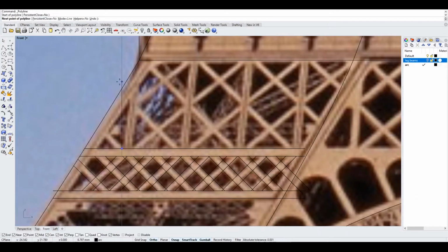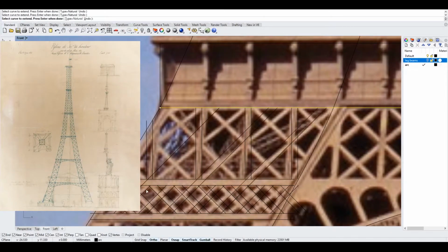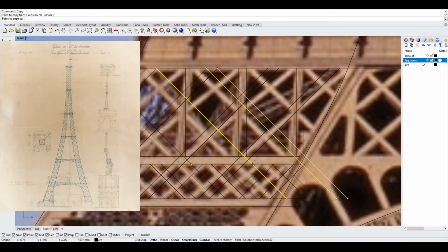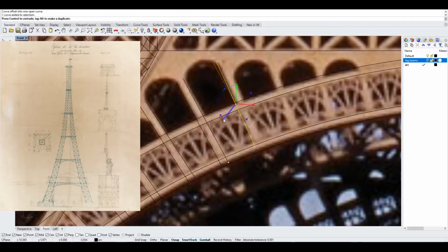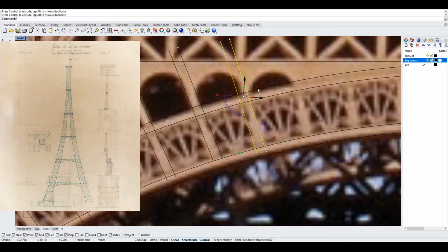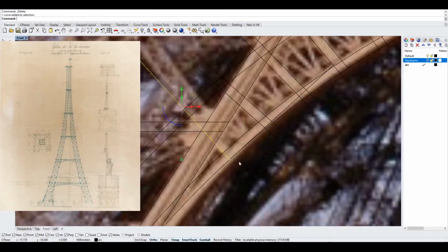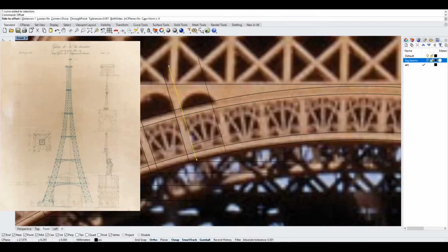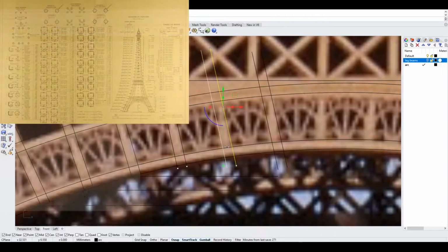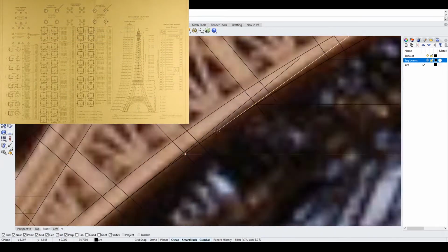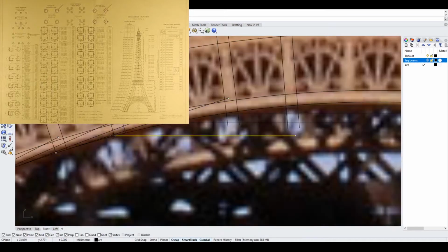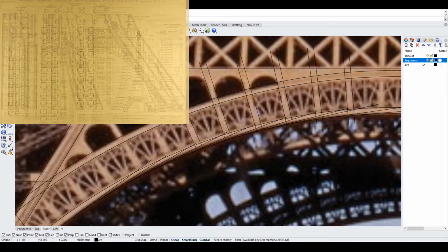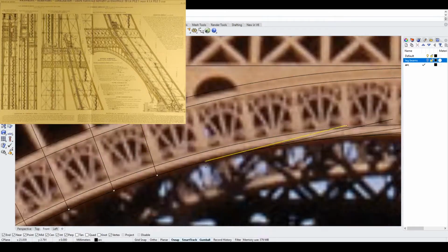Émile Nouguier and Maurice Koechlin, the 2 chief engineers in Eiffel's company, had the idea for a very tall tower in June 1884. It was to be designed like a large pylon with 4 columns of latticework girders, separated at the base and coming together at the top, and joined to each other by more metal girders at regular intervals. The tower project was a bold extension of this principle up to a height of 300 meters, equivalent to the symbolic figure of 1,000 feet.